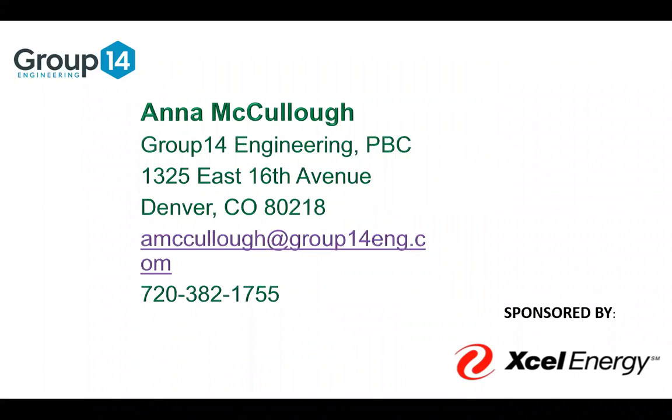And then I've just had one more question. Oh, no, two more. Just had another one come in. So baseline system on proposed versus standard reference. Does the performance software know, or does the modeler have to know? I think that was alluding to whether it's air cooled or water cooled, and do you need to go and look at the footnotes and input that correctly, or does OpenStudio know what has to be inputted? We have to go in and input it. So you need to know.